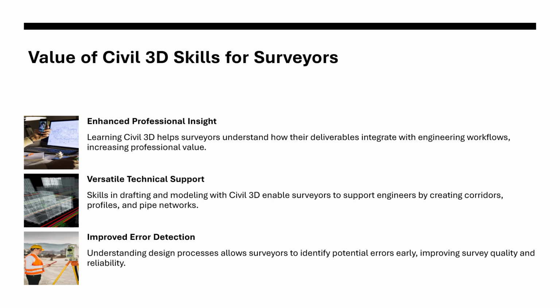And third, these skills sharpen your perspective as a surveyor. When you understand the design process, you'll be better equipped to catch errors or conflicts early. You'll see where an alignment might extend beyond right-of-way, where a profile does not tie correctly into a benchmark. By anticipating how designs are created and used, you strengthen the quality of your surveying practice.